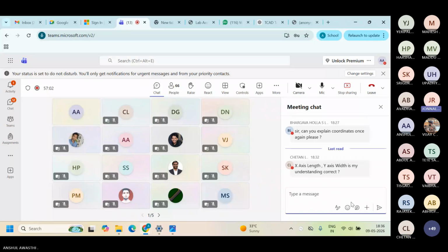So you mentioned that for the coordinates, in between we have a junction, right? PN. First, we directly give the whole length, and then we decide the middle coordinates like that? No. First, we will define the end region. We will start from minus 1.5 and go to minus 1.25. That will be the end region. Again, we go from minus 1.25 to minus 1. That will define our P region. Like that, we'll define. We'll see this.